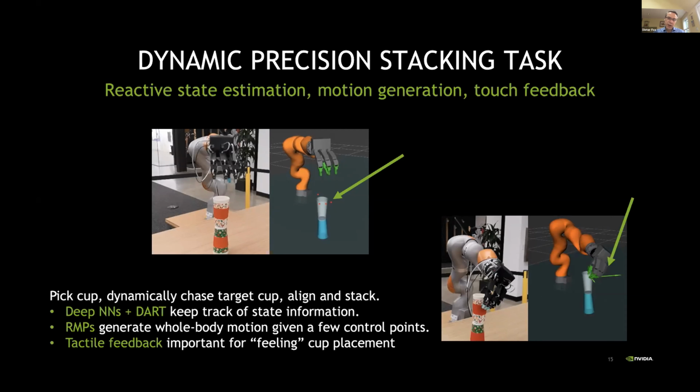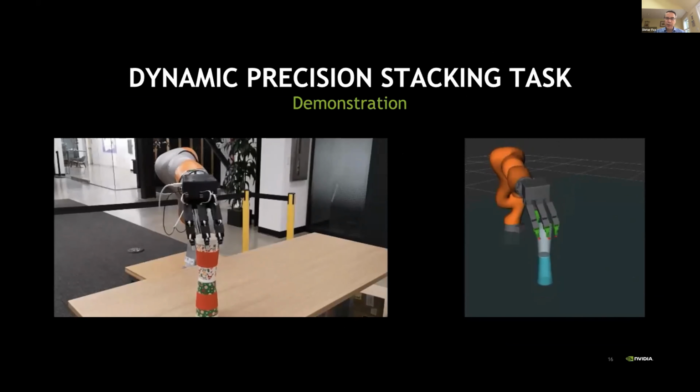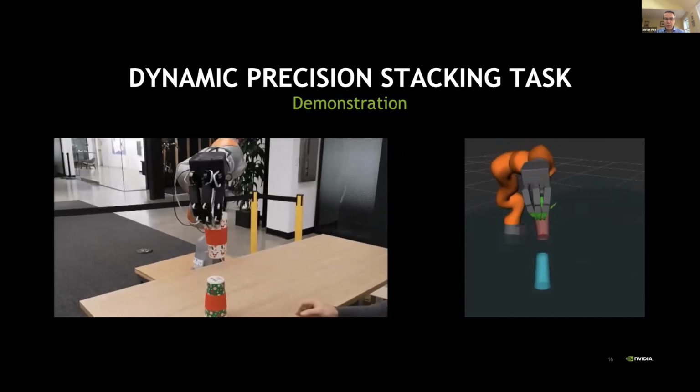And once it's making contact, we're using the tactile feedback that Bala was able to learn based on his data in order to control first how the cup is being held by the robot, and also when we want to place it, to determine when the placement happened. Okay, so I'll show you just a video of how this now works. On the right-hand side, you can see the DART estimate along with the pose estimate, with the detection of these objects.